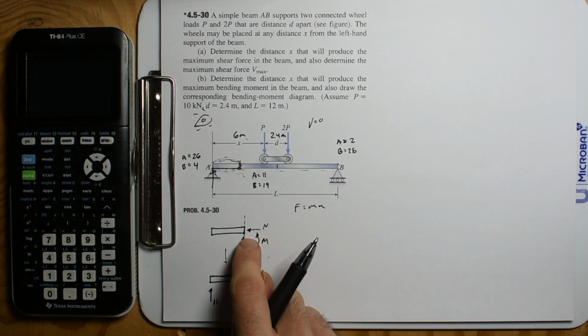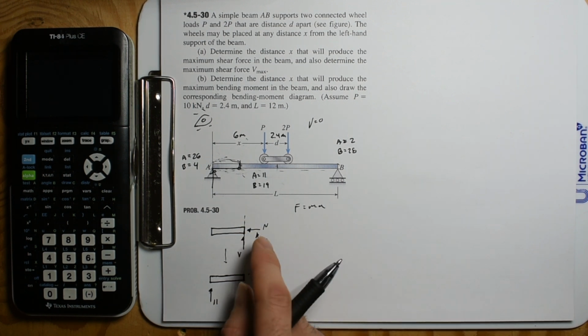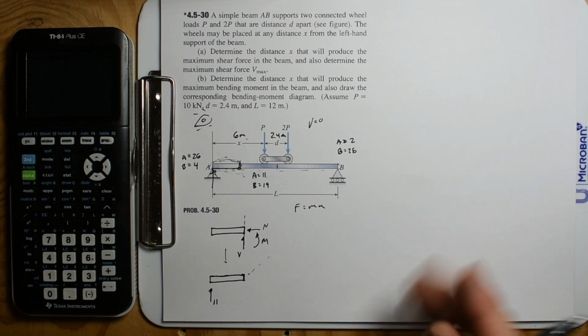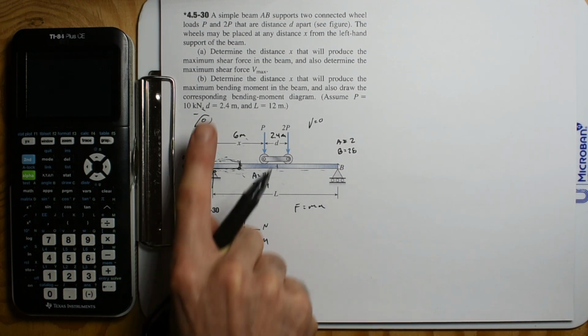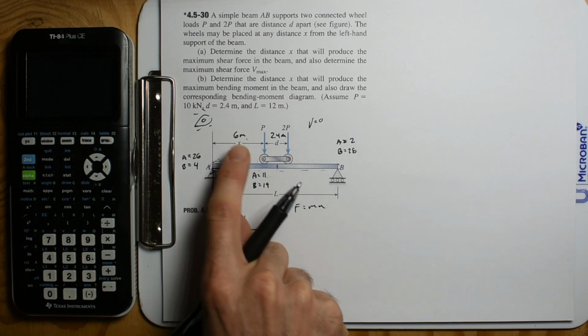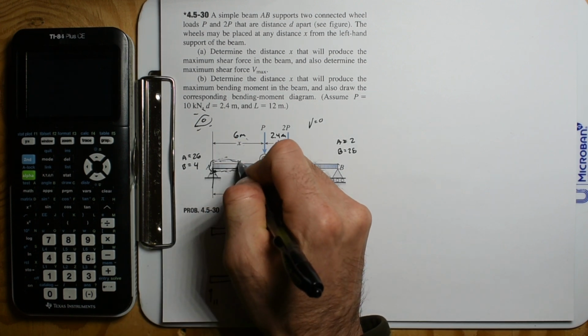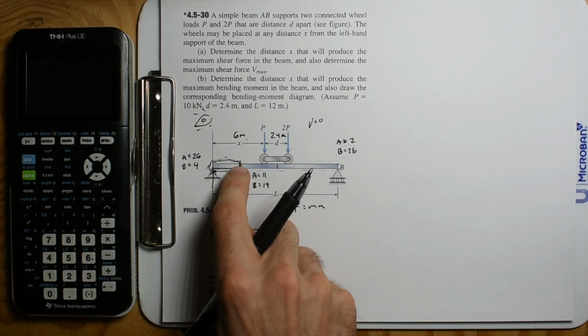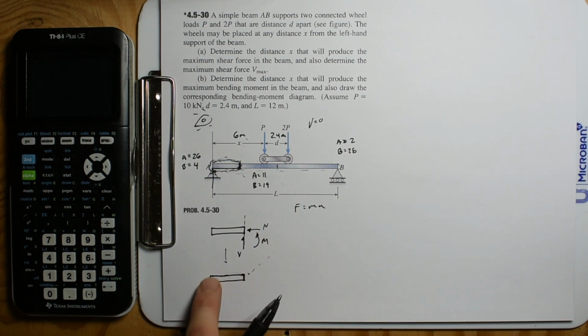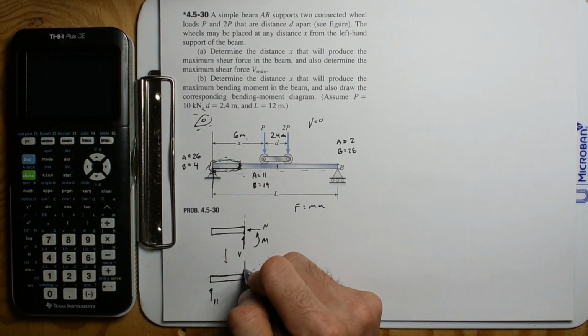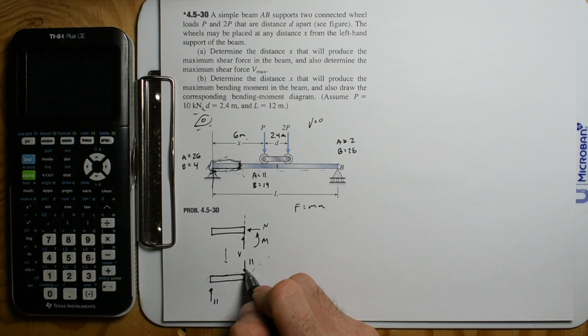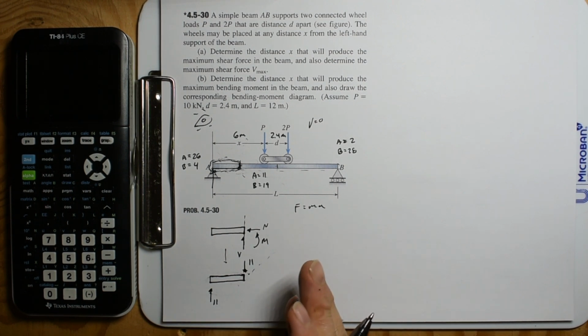I mean, just cutting something out, I don't know where you get all these magical forces, but if you do it from this perspective, you know that there's a force at A pushing this chunk of material up, and you can, just theoretically, make a free body diagram of any chunk you want. If you place it in outer space, put this 11 kilonewtons on, well, it's not moving, so there has to be an 11 kilonewton force there. So booyah, now we're getting into it.